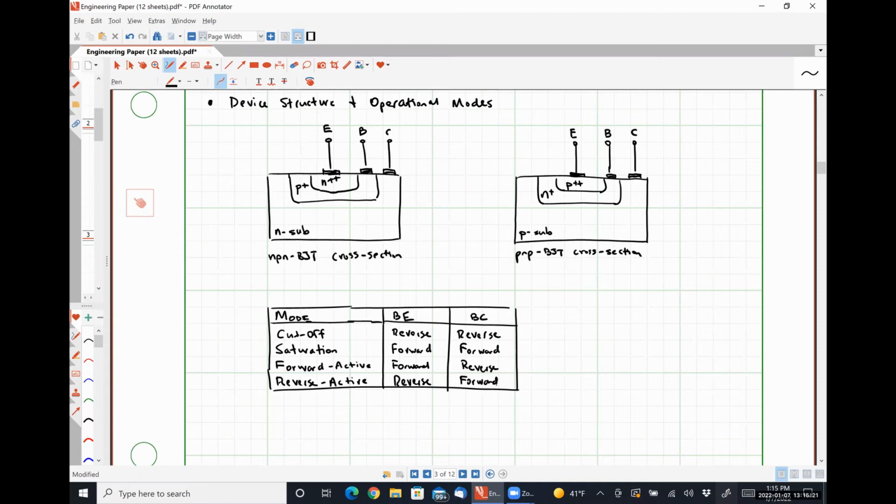We're taking a small amount of carriers from the lightly doped collector, diffusing them into the base, and then using a smaller field to try to sweep those through to flow out the emitter, okay? So generally speaking, we never actually use reverse active region to do anything because it's just doing the exact same thing as the forward active region, except smaller and much, much hotter, okay? So that's how you burn them out.